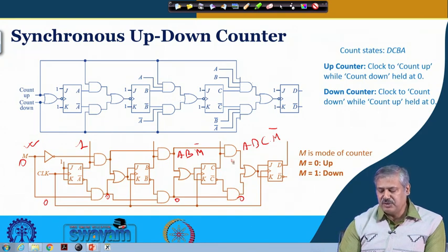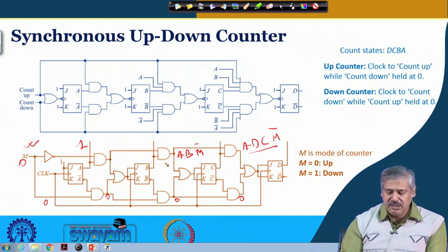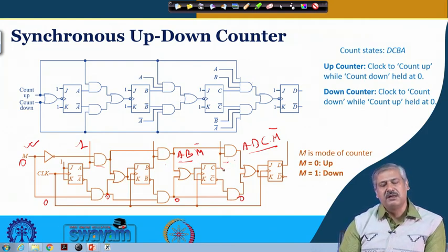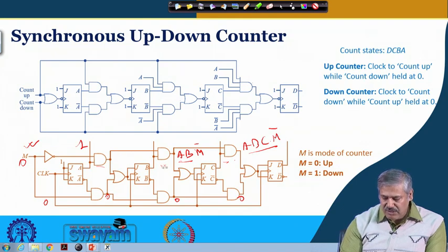So, you can have a 3 input AND gate also, like the one that you had seen before in this case instead. Here we are only having 2 input gates in all the cases, because we are feeding the AND gate output of the previous stage. But remember in this case there is a small accumulation of delay, because this delay gets accumulated.